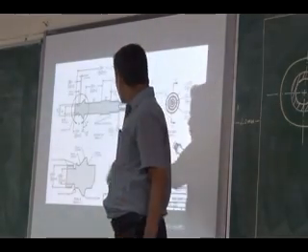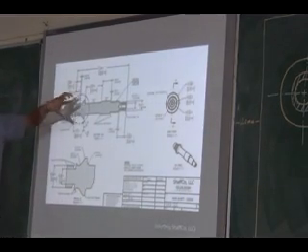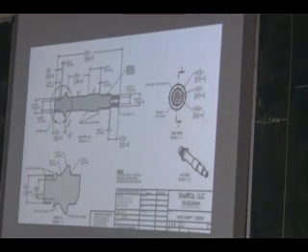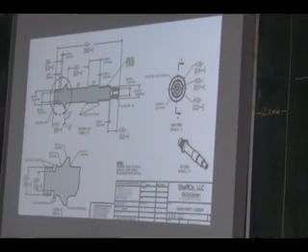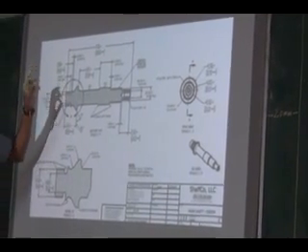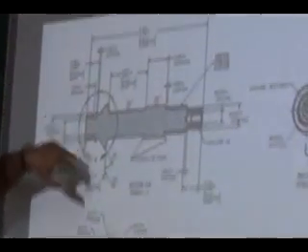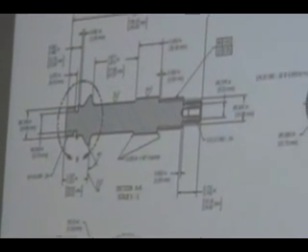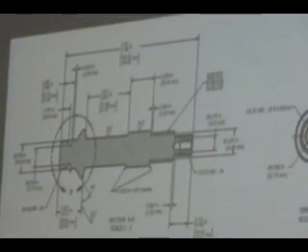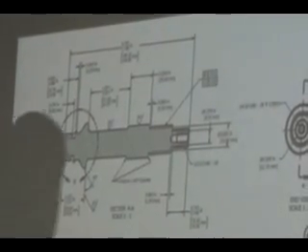I want to see the details of this particular area because it is too small in my drawing. It contains very small details, and there I am not able to represent the dimensions and details. So in my drawing I just encircle that region and enlarge it, showing it in a separate view. Whichever region you are interested in, you can show as a separate view, in which you can conveniently show your production design details.